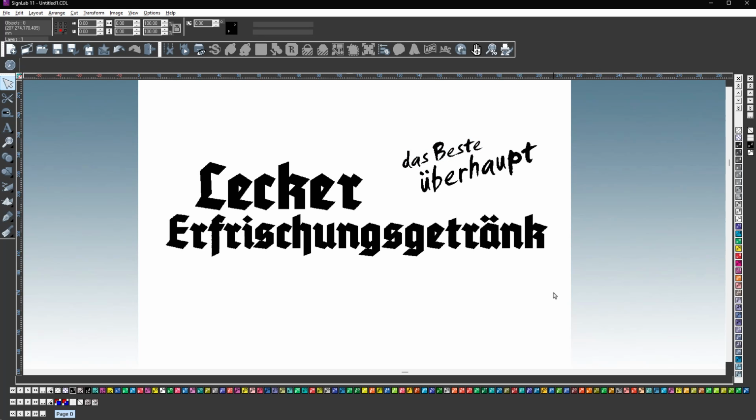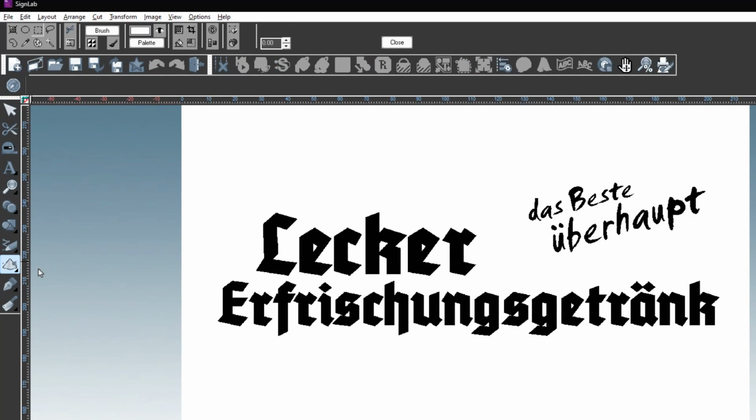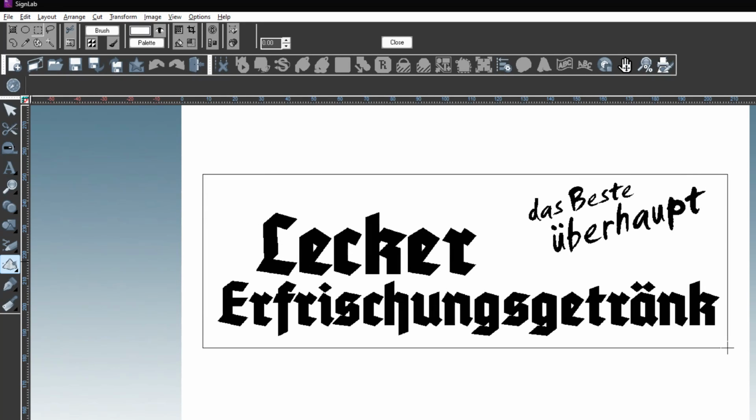To select only the block text with sharper angles, select the graphic and go to the Scan Tools icon on the right, and click on AccuScan. Go to the Select tools found in the upper left of the window, and click the Rectangle Select tool. To start, click at the top left of the full logo, and drag to the bottom right, surrounding the entire logo. Next, we want to remove the script text from the selection.